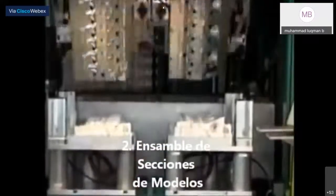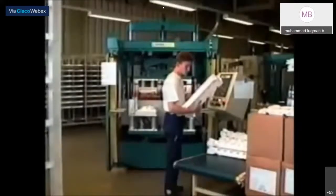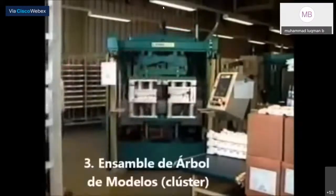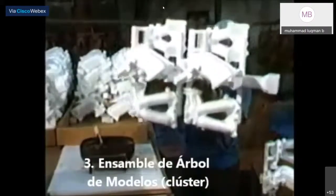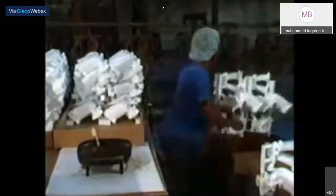Excellent dimensional tolerances, appearance and casting quality can be achieved when flat glue lines are properly designed and when tooling and equipment have proper precision and control. Foam replicas are then assembled with a gating system to form a cluster of parts to be produced in one flask. This can be done manually or by machine.